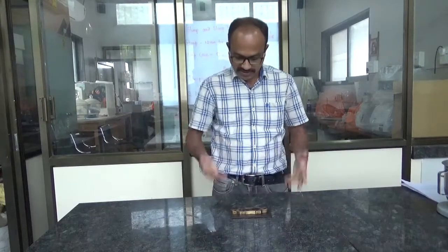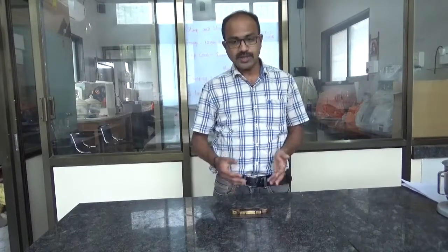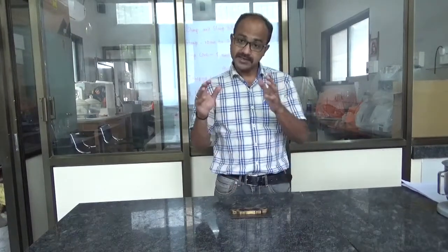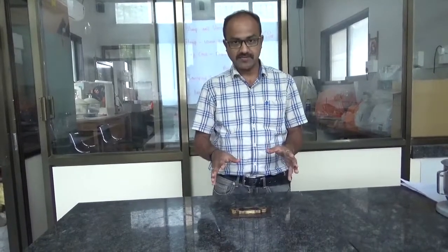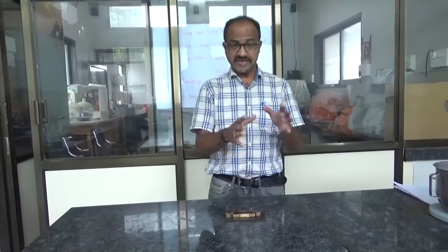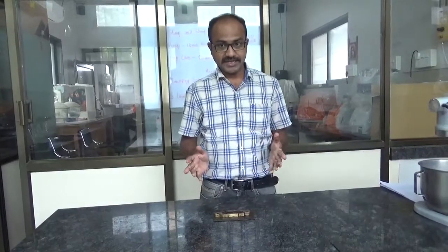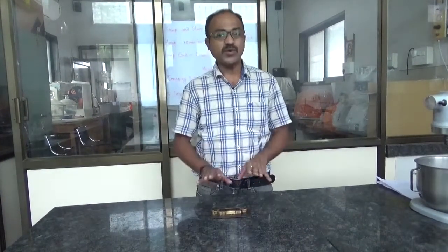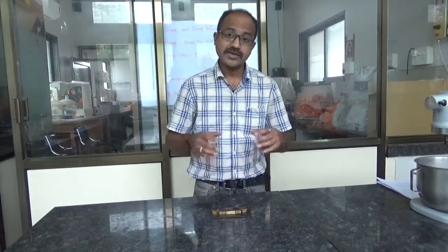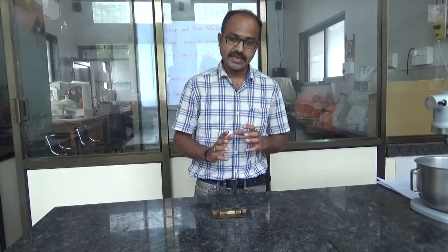Once again, I am going to keep my sample in a ductility machine, whose temperature we are maintaining at around 25 degrees centigrade, for around 1.5 hours, immersed in the water. After 1.5 hours we are going to test this sample.